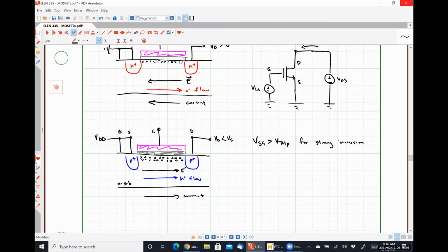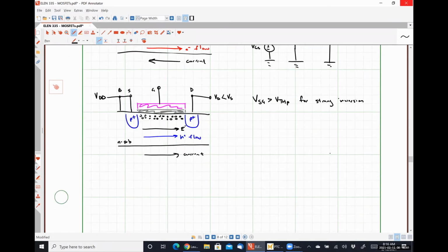In the book, for whatever reason, in its illustration, it shows that the drain current is flowing from the drain to the source and then introduces negative signs in key places in order to make that true. That to me is very, very confusing, okay? So instead, we can see that the Pmos transistor behaves exactly like the Nmos transistor, except we just have to switch the subscripts on our voltages and everything works out exactly, okay?